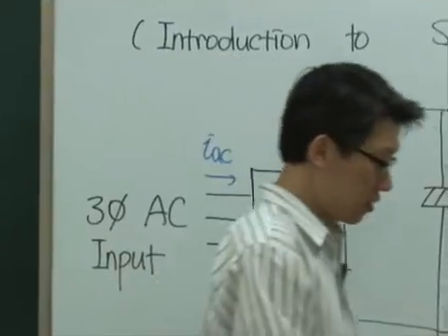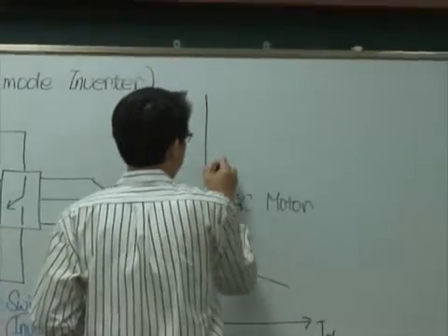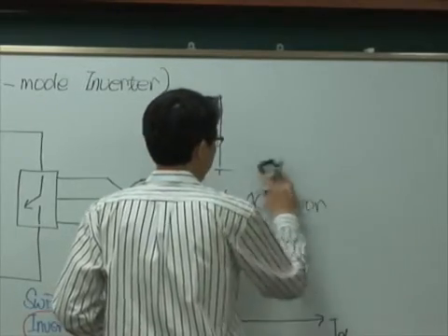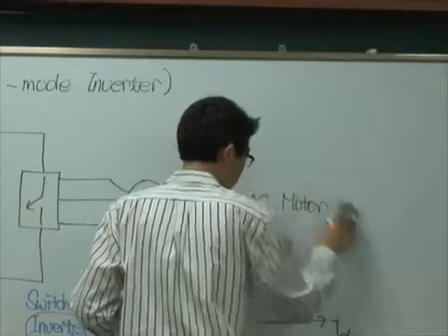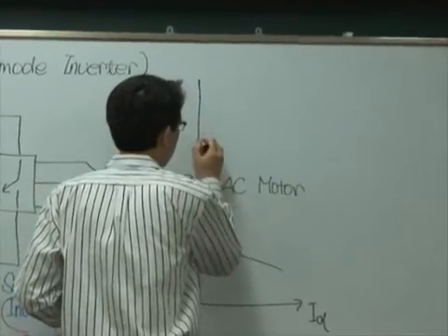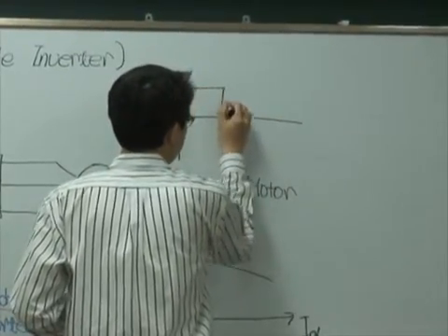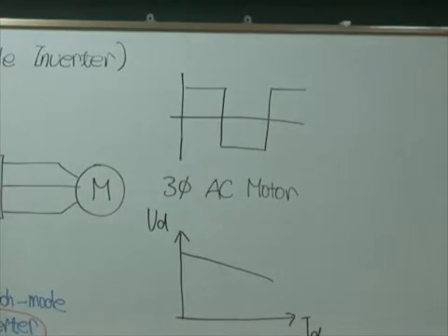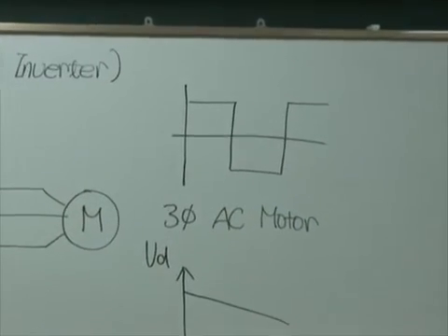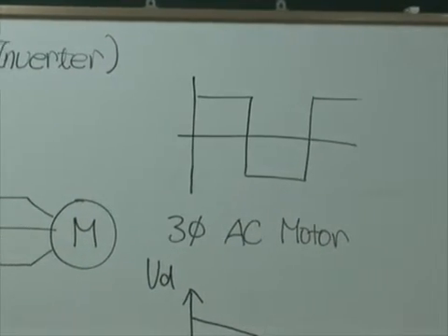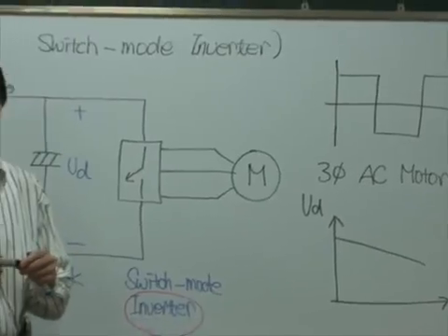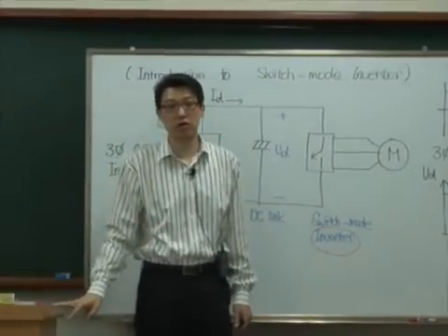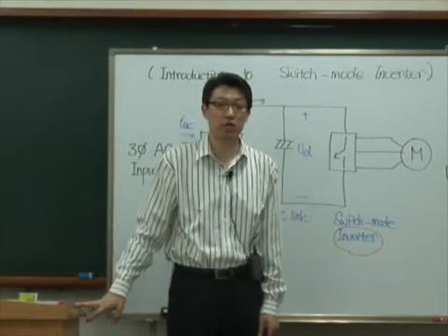Do you remember for the diode rectifier, how did the AC current look like? It looked like this, if we have a constant current source at the DC link side. And how much was the THD? It's almost 50%. So it's by far higher than the regulation limit of IEEE 519.